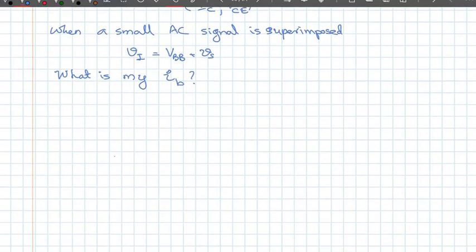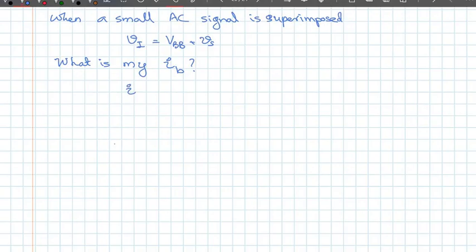Now we know the total current should be equal to, let's call this IS over beta times, this is using the Ebers-Moll equation but neglecting the leakage part. Okay, so this is e to the VBE over capital VT, because it's a constant.